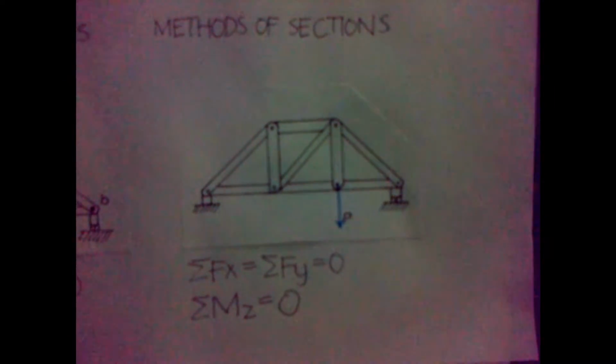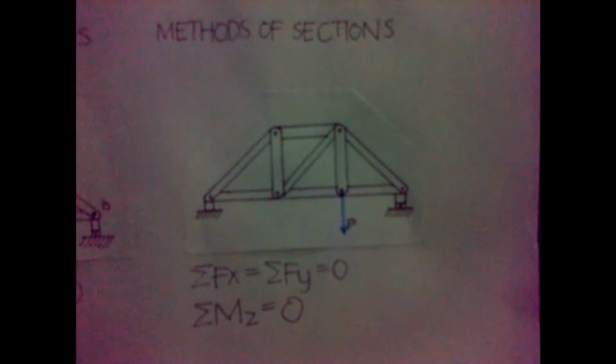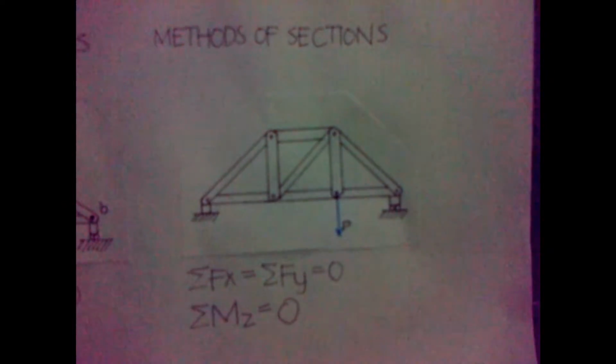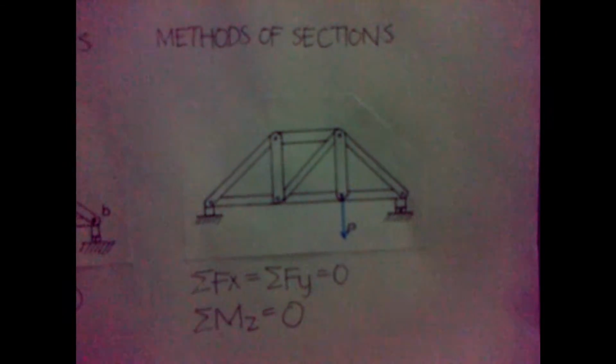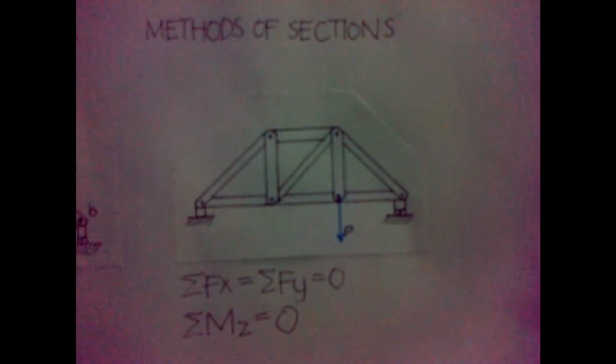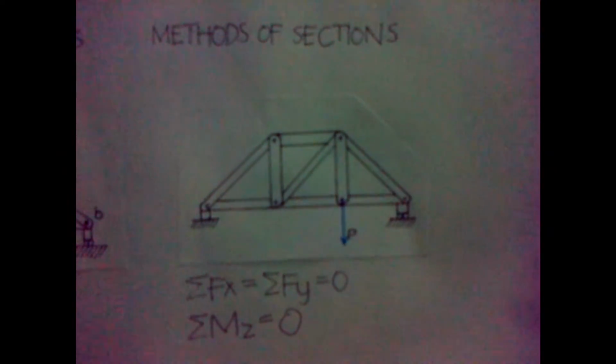First, the truss is split into two sections and all cut members are replaced with an unknown member load. Make sure that only 3 members are cut for a two-dimensional truss. The unknown member forces are then treated as external loads and can be determined.